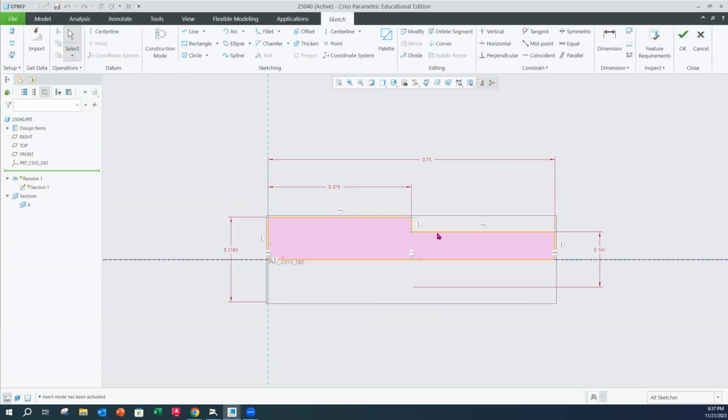And how I created the portion that is threaded, which is this part right here, is I used the 0.216, which is the largest diameter of that thread. That's going to be the outside diameter, representing the tips or the highest point, the major diameter on those threads. The rest of it was pretty basic, but I did revolve it around a center line.